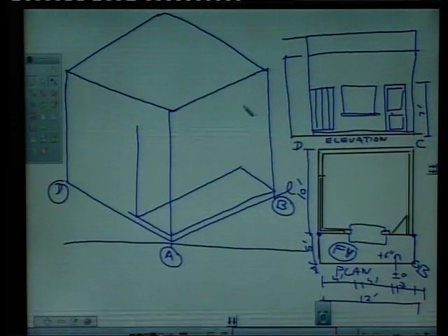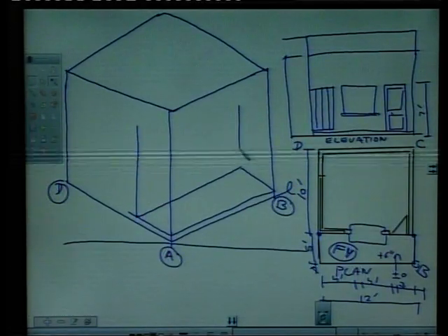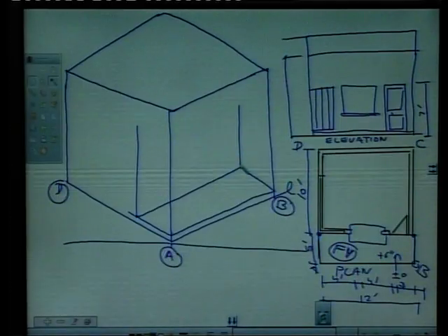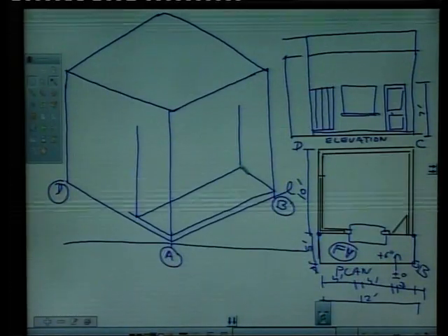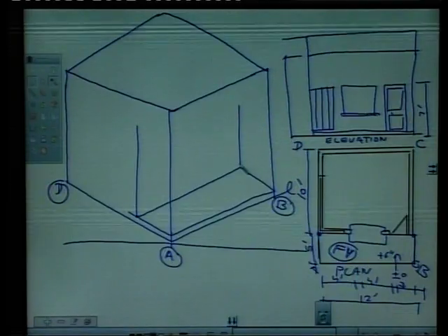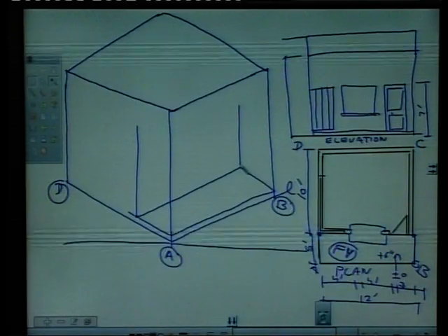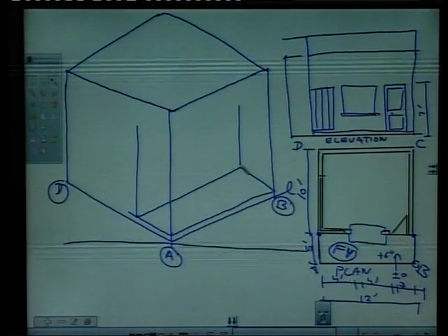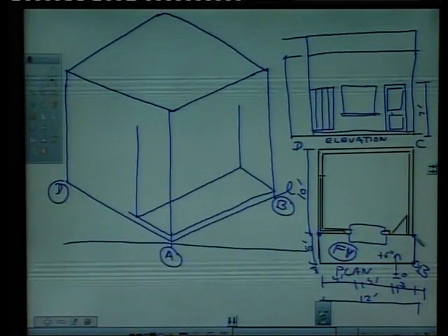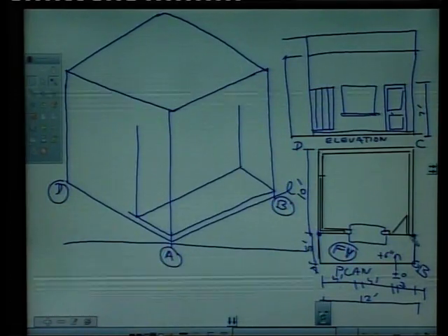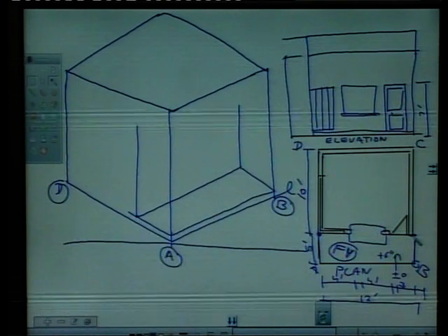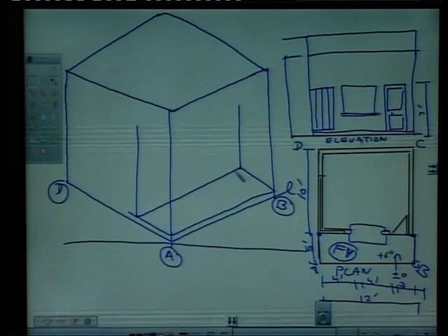And a vertical line from here. As per principles of isometrics, vertical lines remain vertical. Okay. Next, say start from here. Here we have a wall of say 9-inch wall. So mark to the scale 9-inch here.